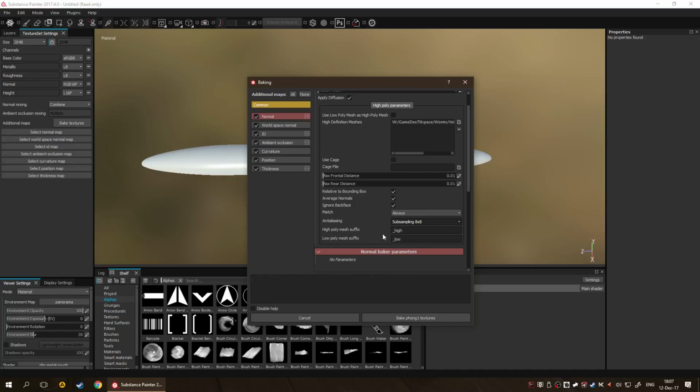Then you've got the prefix and the suffix when you've got the high and low polys. Remember, it doesn't matter what comes after this as long as the name of the meshes matches beforehand. So in your FBX file, whenever you're creating a gun, make sure that you've got, for example, barrel underscore high and barrel underscore low in your high and low meshes respectively. Obviously, it doesn't matter what comes after this, as long as high or low is matched.